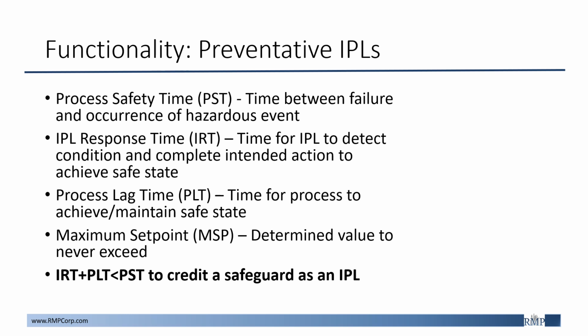The next time that we'd like to consider is the IPL response time. That is the time for a given IPL to detect an out-of-limit condition and to complete the actions intended to achieve a safe state. So the key words to note here are detect and complete the actions associated with the IPL. Once the response time is considered, the end of this time is when the process lag time begins. So this is the time it takes for the process to achieve or maintain its safe state.